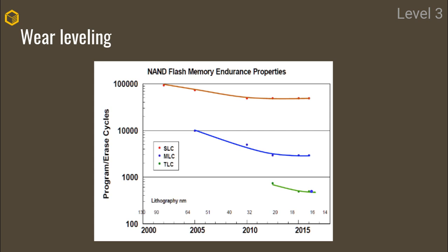And so in order to maximize the lifetime of my device, I am actually going to try and spread out as best as I can which cells I am writing, in order to not always wear out the same cells and not have them lose my data because, well, they're dead. And as we move to most recent technologies, you can clearly see how this is becoming more and more of an important role for our memory controllers.